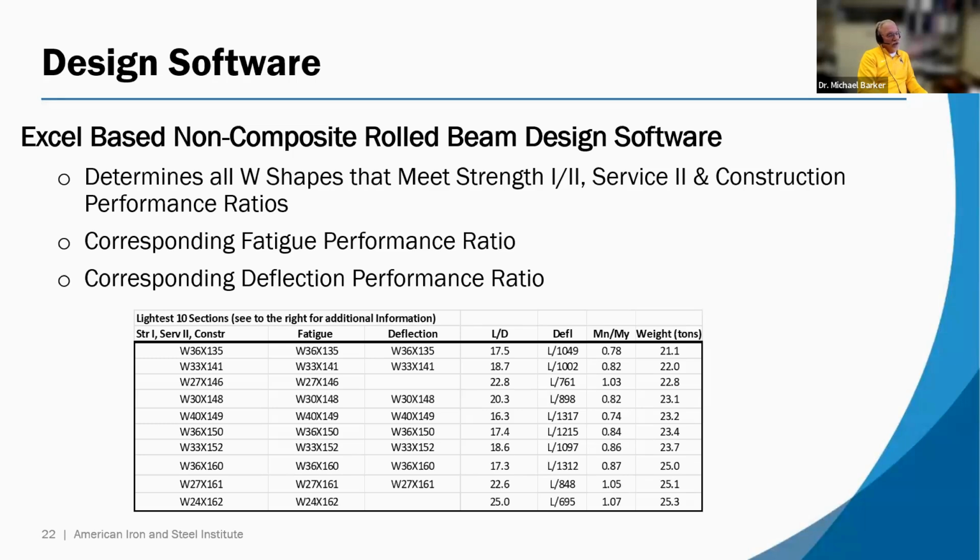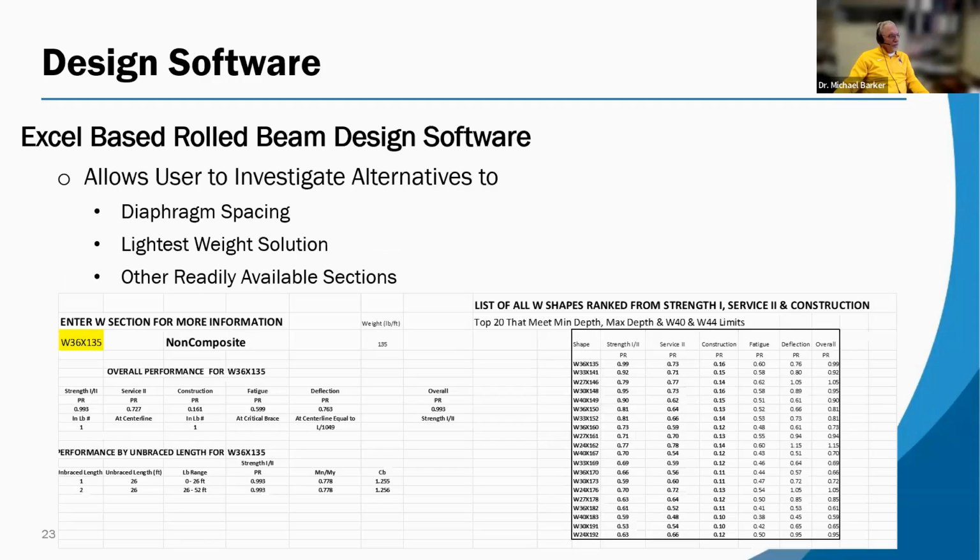It's at a deflection of L over 761, and our limit was L over 800. That's probably close enough. We could live with that if we wanted to go heavier but shorter because of approaches or clearance. But it gives us options here, whereas that E-span 140 doesn't quite get to that level.